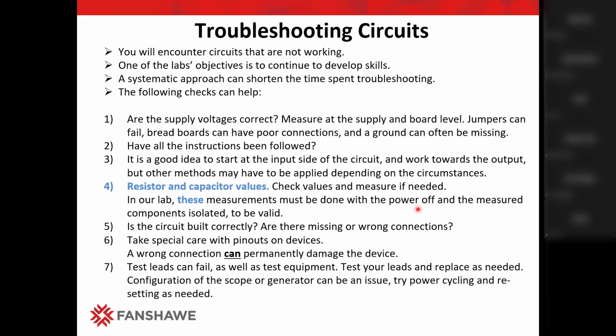However, as you go along, if you know the circuit that you're troubleshooting, sometimes you don't have to take that resistor out of the circuit to see if something is good or not, because you'll be expecting certain values at certain places. However, when measuring resistance, power has to be shut down. That's a given.